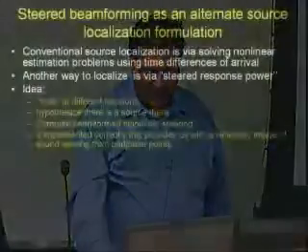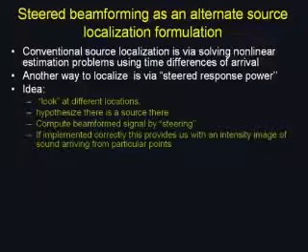And when we do source localization via audio, you want to use microphone arrays. There are many approaches to doing source localization using microphone arrays. The oldest techniques are based on solving geometrical nonlinear estimation problems. Essentially, you take time delays of arrival between microphones, and you try to solve for the source location by solving some nonlinear estimation problem. But this approach, especially in the presence of noise and reverberations, is known to be inaccurate.